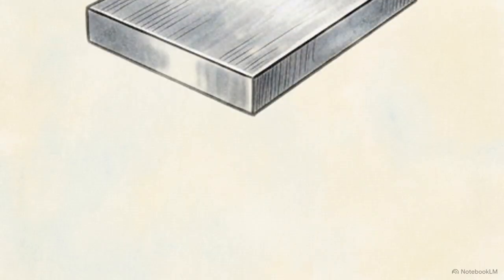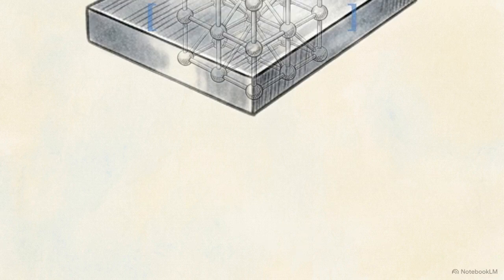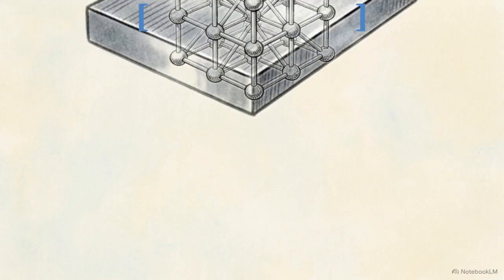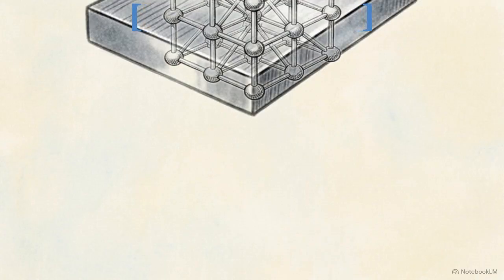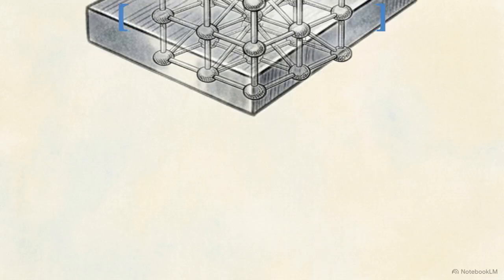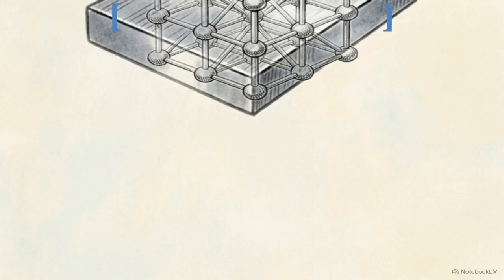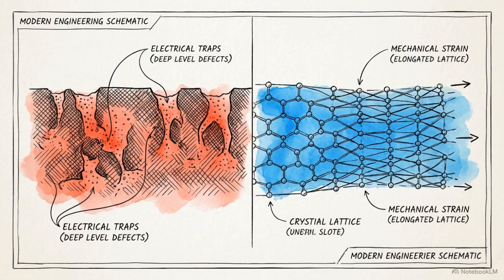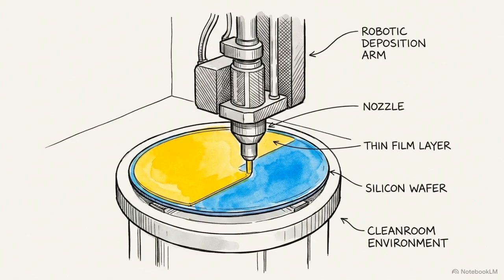Modifying the nanoscale thickness of silicon nitride actively alters the charge dynamics of the two-dimensional electron gas, or 2DEG. Changing this initiates a competition. Electrical trapping captures electrons at the surface, while the material's physical presence applies mechanical strain, pulling on the underlying crystal lattice. Tuning the performance of a heterojunction device requires mastering the precise mathematical balance between these two forces, rather than simply applying a thick coat of dielectric and walking away.